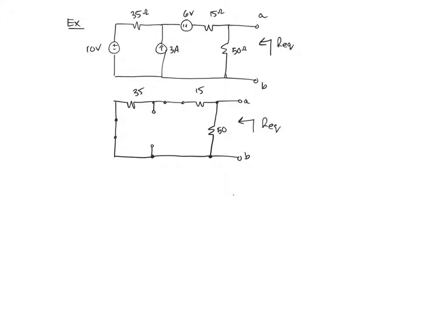So we know actually, just by inspection really, that the equivalent resistance is going to be 25 ohms. But let's use the source driving technique. What we're going to do is attach an independent source to the load. I'm going to make this a current source of value 1 amp. And my objective is going to be to find the voltage dropped across that current source, V sub SD.